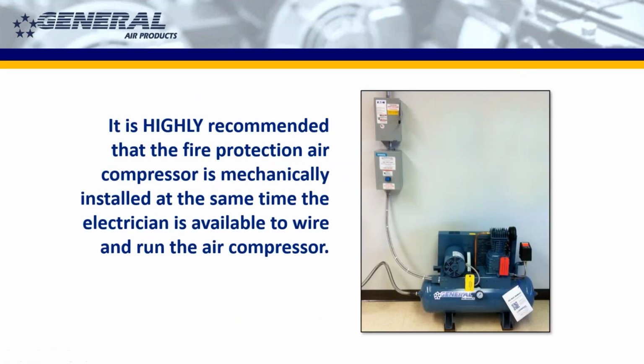All right, so here's another recommendation for installation. Now we've got it out of the box. When you take it out of the box, one of the things that I highly recommend is doing the mechanical installation at the same time the electrical installation is going on, so that even though you might not be electricians, you can watch what's going on and see if it's running properly once the electrician's done their work.